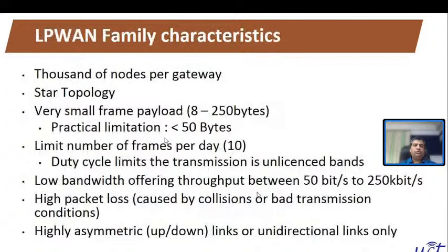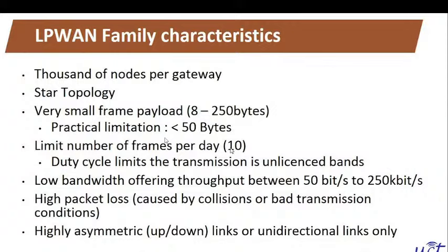If we talk about low power wide area network, it can have thousands of nodes per gateway. It would have a star topology and a very small frame payload. We cannot send very huge data. It is used only for controlling and monitoring purposes. We cannot do streaming and other things. And it is the number of frames per day; we can send a limited number of frames, like up to 10. Duty cycles are limited, and we have low bandwidth.